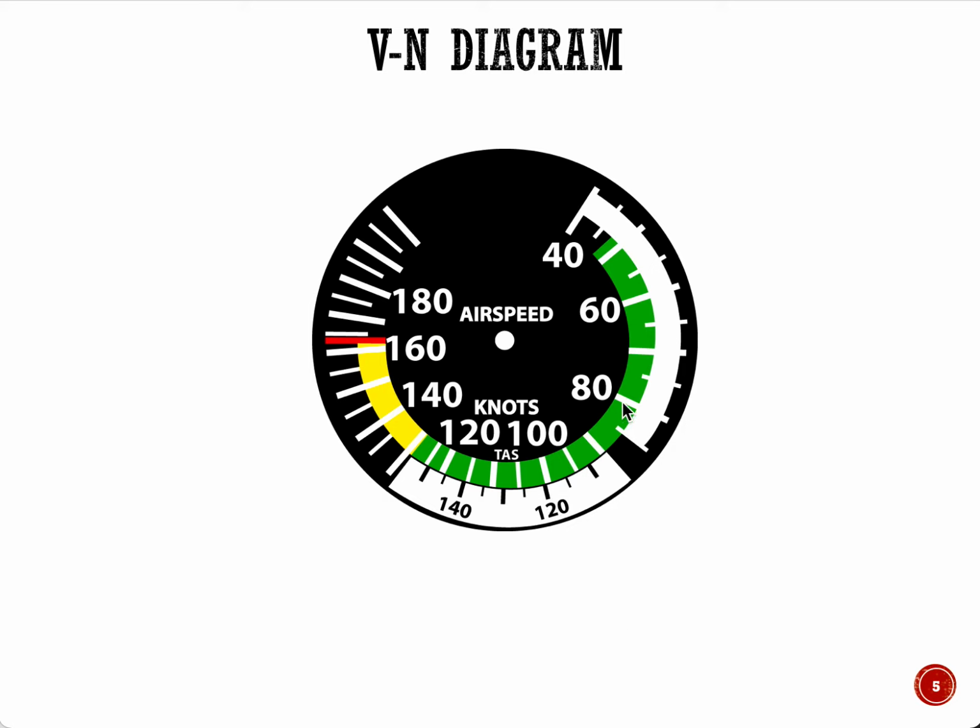We'll walk through a little bit about what these colors and the lines represent. Obviously this is a dial going from a speed of 40 knots to about 200 knots here, but there are color codes as well, which indicate certain things. Starting with the lower green dial right here, that essentially represents the 1G stall speed. 1G in the sense lift equals weight, correct? Lift required to lift the weight of the aircraft, at 1 times the weight of the aircraft.